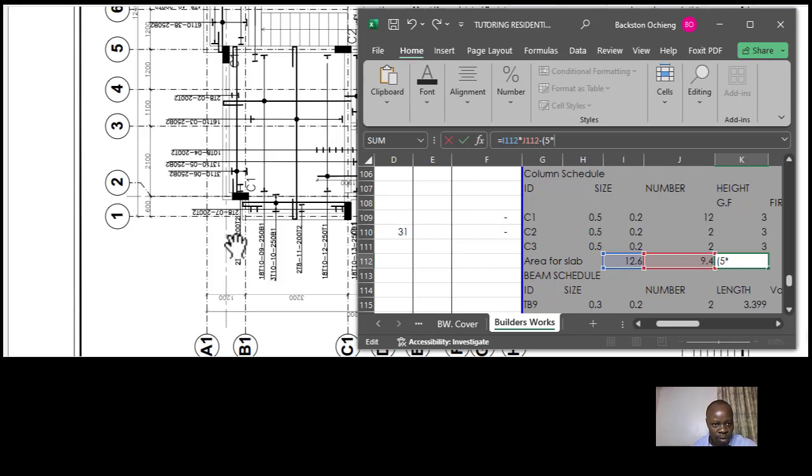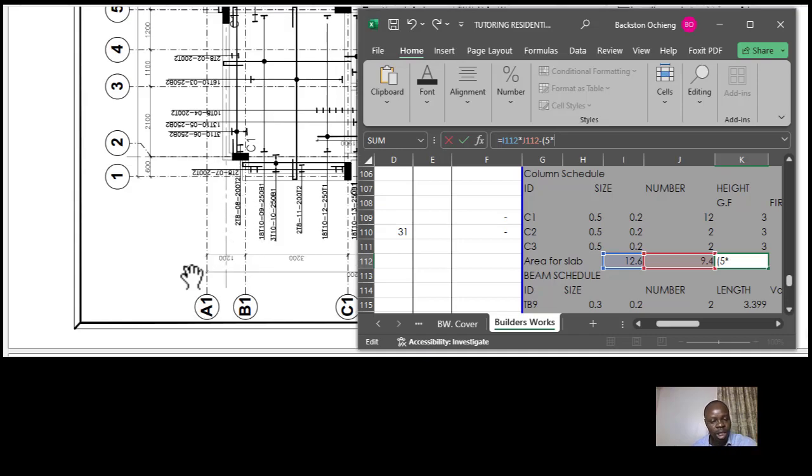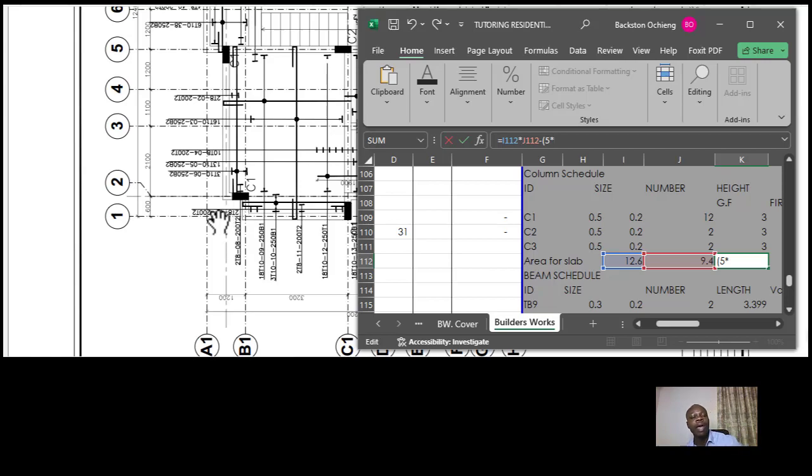So what is the width of that particular point? You can see here that particular length is not indicated, but from our previous work we had confirmed that it's 0.6, from the architectural plan. I'd just like to emphasize that whenever you find that some dimensions are not shown on the structural plan, then you need to reference them from the architectural plan. We did so in our previous session, and it was coming to 0.6 along the centers.